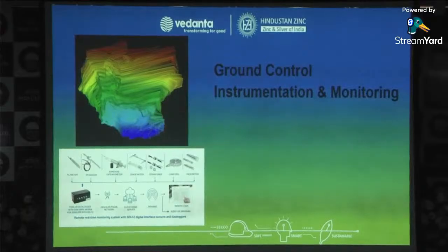Sir, we have hangwall quartz mica schist, and strength is somewhere around 130 megapascal. But sir, again, if some hangwall still fails, we have the remote loader, sir. No one has to go inside the open stope area. We are operating it remotely, and if something falls, it will happen on the LHD itself. No person will be in danger.